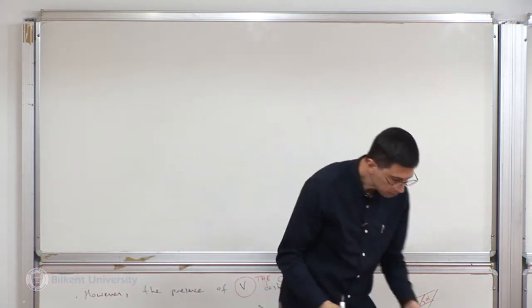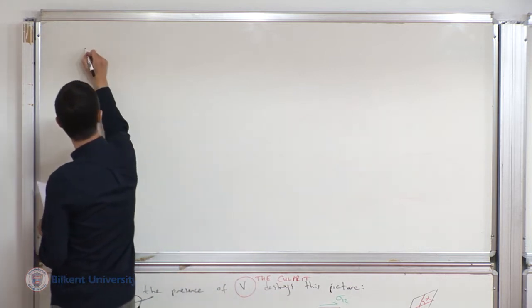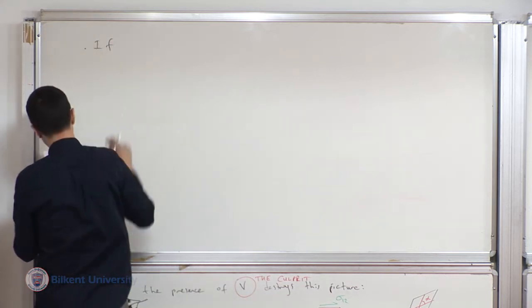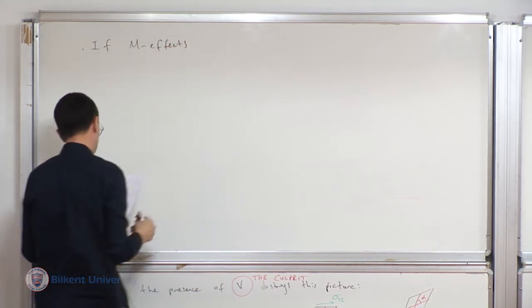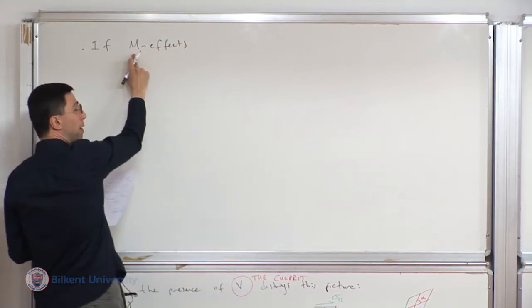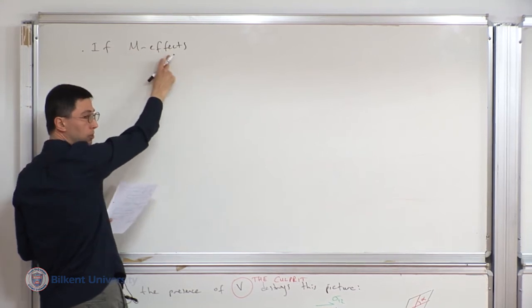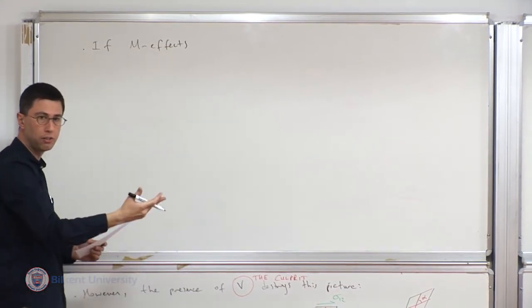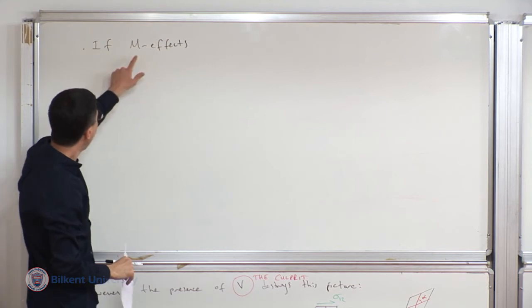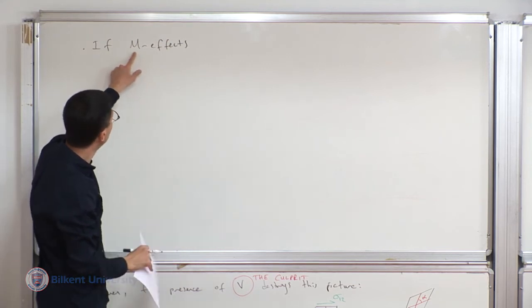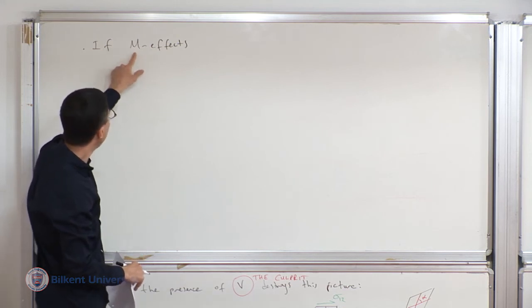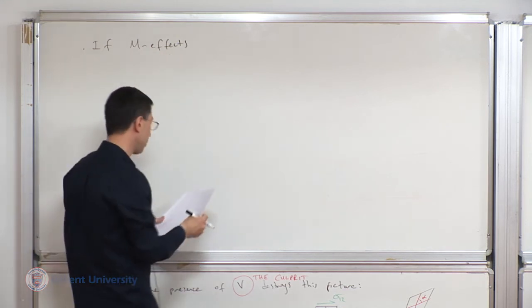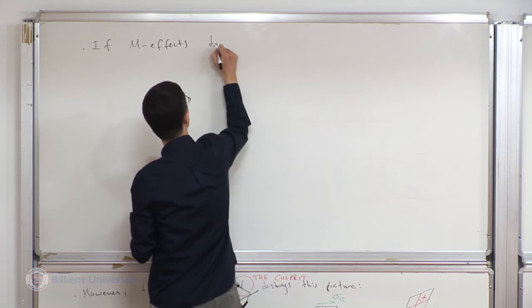So now I'm going to state, again, a statement that I had verbally expressed last time. Suppose, in particular I'm talking about the effects on deflection or deformation, I am going to assume, hope, that the bending moment effects dominate shear effects.